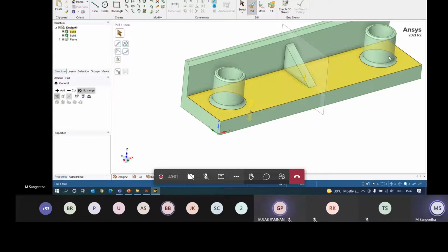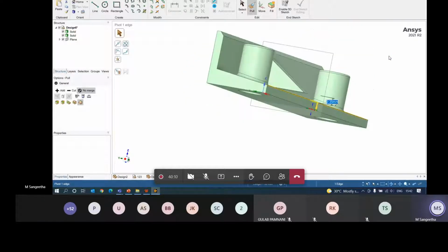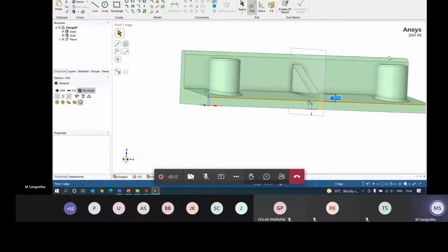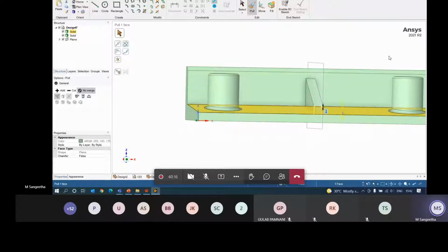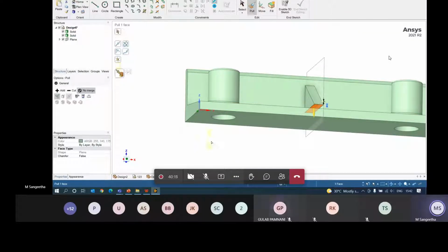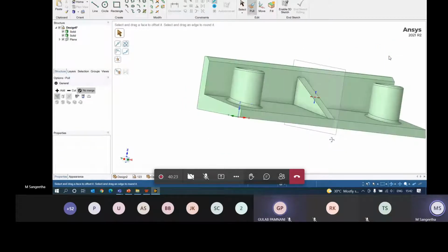And then if you wish, you can also have a pivot. Let's say I want to make some modification like this. So you can see your geometry is modified, and suppose the surface you want to make it touch, select the internal surface and say up to selected surface. So now this is modified, right?